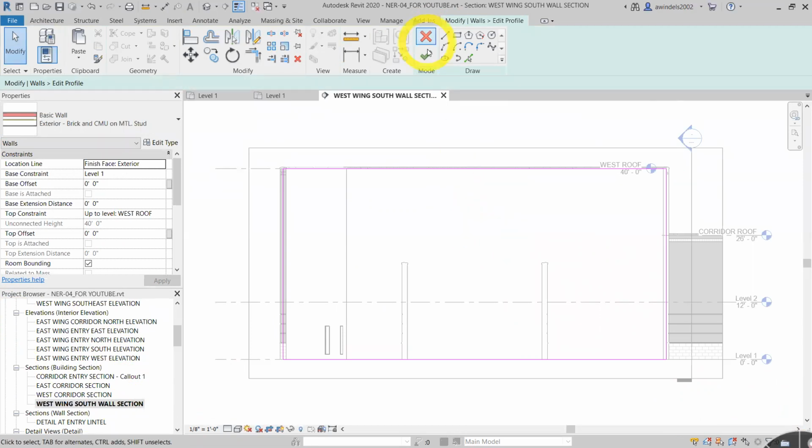and it's trying to tell us in the book that we can tell we're in sketch mode, obviously because of the magenta, but you'll see a finish edit and cancel edit mode too. Those are pretty obvious giveaways with our draw commands that you're also in it. Let's look at the options bar, and we're going to say split element first, which is right here. And it wants us to select the delete inner segment, so it deletes it out without us having to do it after the fact.